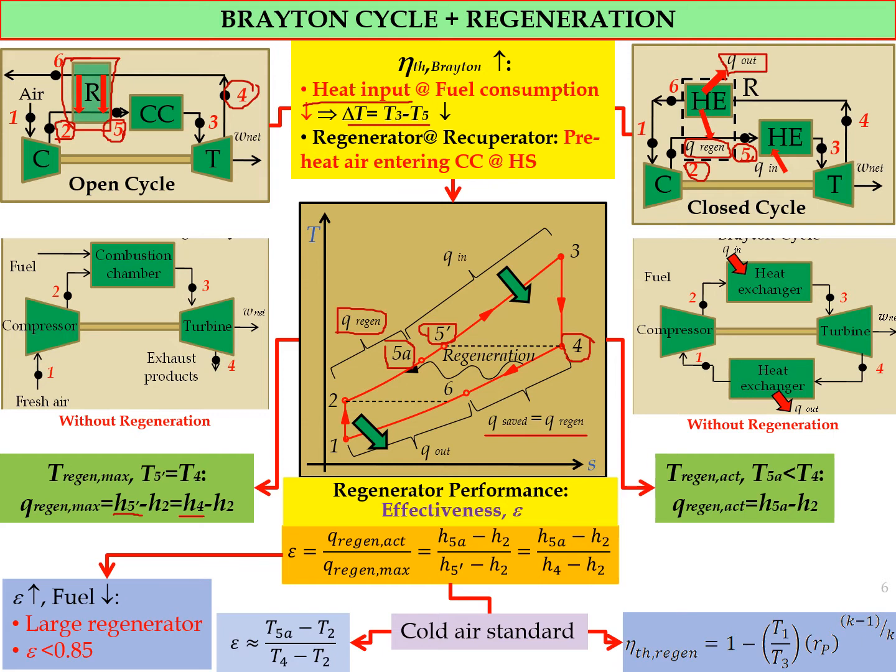the fuel. However, to get the optimum or higher efficiency or effectiveness, we will need a larger regenerator, which is not cost effective for the system. So in normal cases, the effectiveness of the regenerator is less than 0.85, or less than 85%.